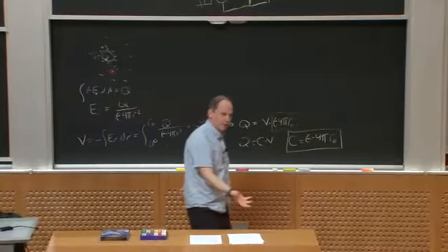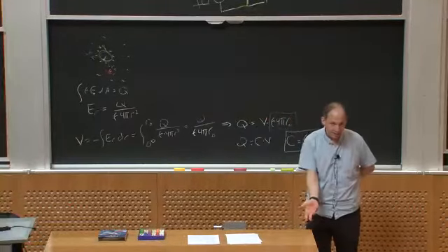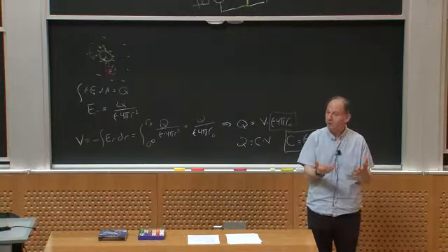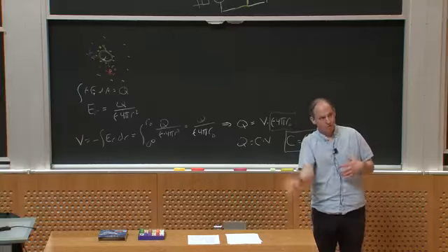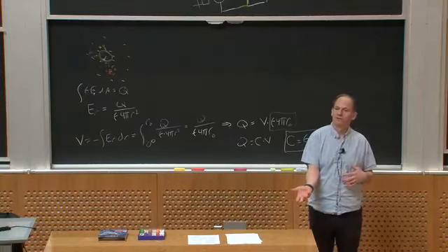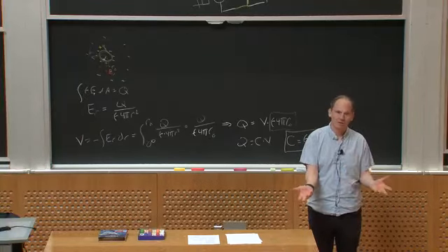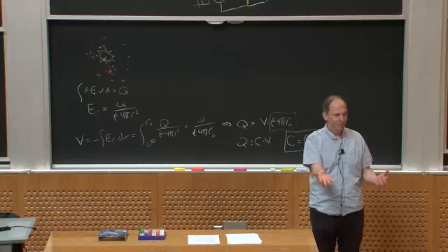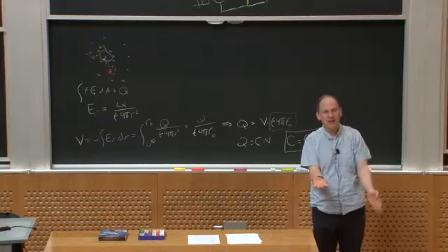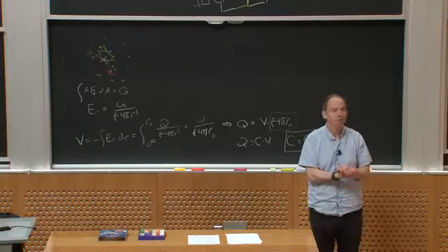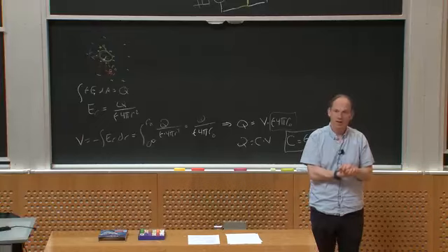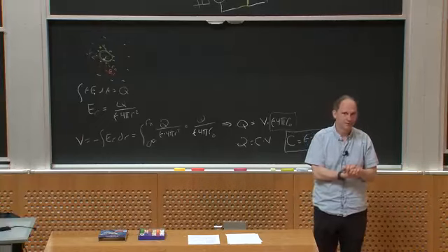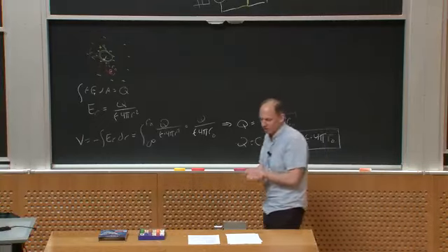If you're going to go analyze a Cuk converter or some other kind of converter, which loop you care about is different. Which nodes you care about are different. But they're usually the ones with the square wave currents in them and the square wave voltages on them, or the high dV/dt or dI/dt elements on them. Okay? And small changes can make a big difference. Questions about any of that?